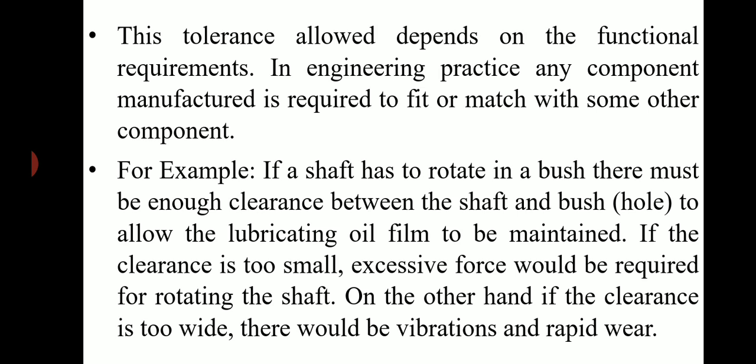In engineering practice, any component manufactured is required to fit or match with some other component. For example, if a shaft has to rotate in a bush, there must be enough clearance between the shaft and bush hole to allow the lubricating film to be maintained. If the clearance is too small, excessive force would be required for rotating the shaft. On the other hand, if the clearance is too wide, there would be vibrations and rapid wear.